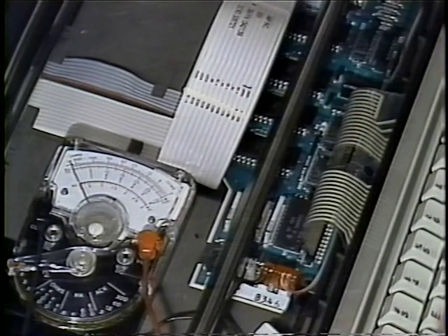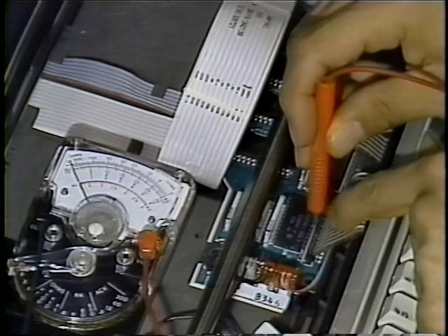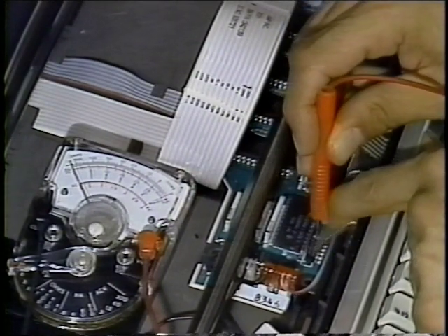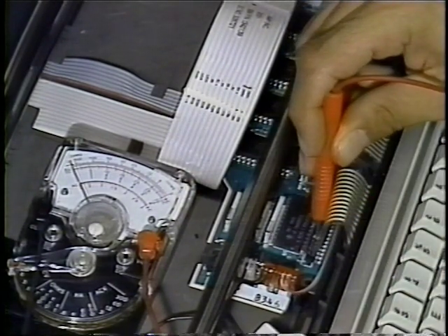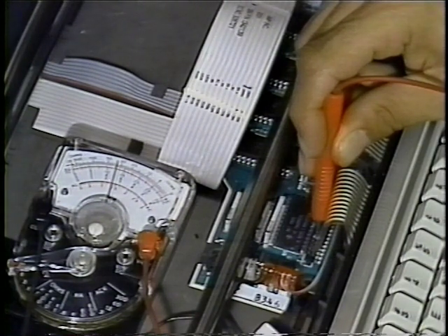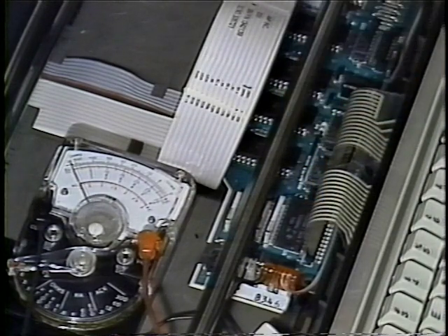To check a drive line, probe the J1F connector pin for that drive line. When a key button that uses that drive line is pressed, the meter should read more than 1 volt DC, and less than 1 volt DC when no key buttons are pressed.